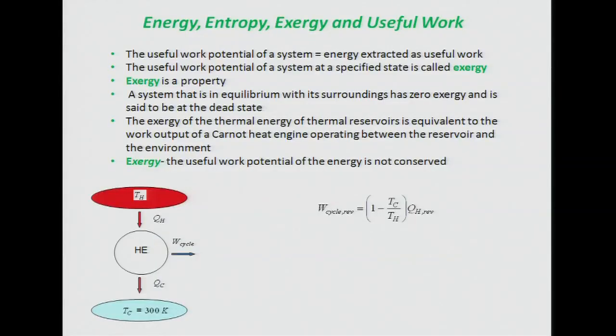Okay, so now let's go back and consider what exergy actually is. Its definition is just energy extracted as useful work. We call it exergy. It's a property of the system because energy is a property. Any system that's in complete equilibrium with its surroundings, so there's no temperature differential anywhere across the system, has zero exergy. And we say that that particular system, which is completely equilibrated with the surroundings, where nothing can happen, is in a dead state. Because how would you get it out of it? You'd have to do something to it. You'd have to change that system to do work on it.